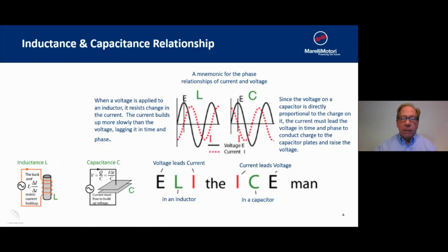Now, when someone applies a power factor correction capacitor, the current leads the voltage, it pulls it the other way. So what the goal there is to pull those back into phase with the capacitors. So unity power factor is the goal for many, but usually you come close. Sometimes you only correct to a 0.9 because that's all the utility rate structure demands.